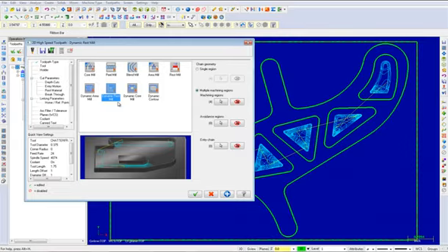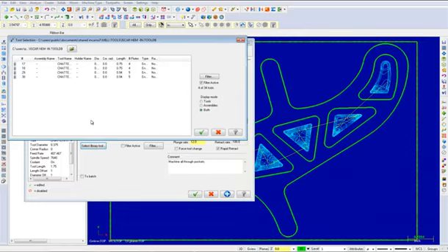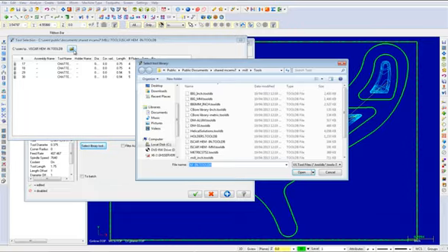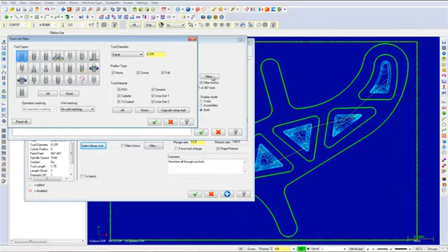From the Tree View list, choose Tool. Click on the Select Library Tool button and then choose the New Library button. Select the following tool list and click Open. Choose the Filter button. Under Tool Diameter, pick Equal and input a value of 0.125. Once complete, select the OK button to exit the tool list filter.